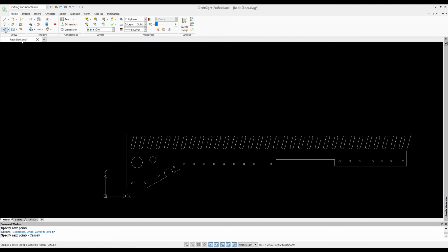I don't want to make it too weak by putting too many holes right along in between. The more holes we put in it along here, the easier it is going to be to bend it when we hit something. But at the same time, I don't want it to be filling with junk. So let's just put a couple holes in here. That's not too bad. So let's go ahead and actually put them there for real. Let's just delete them.